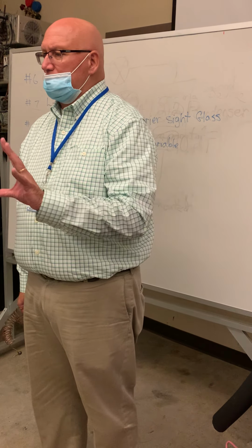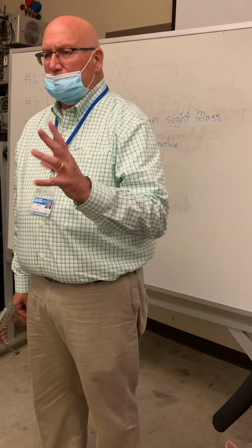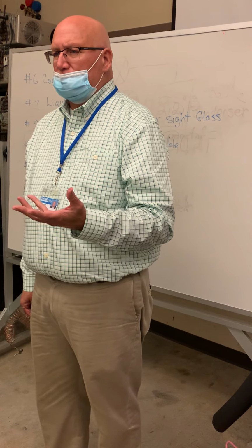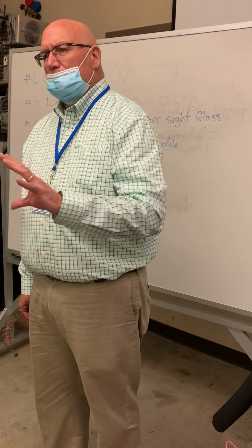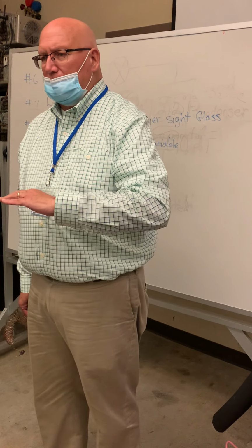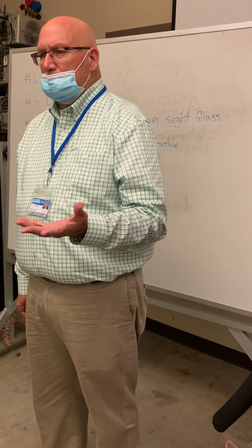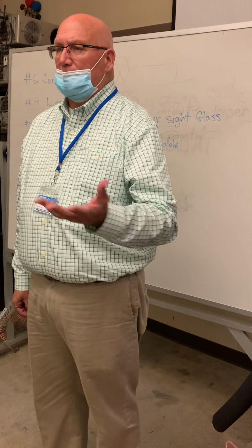Now, I'm using typical summertime temperatures, about 3 o'clock in the afternoon. So I know what the general ambient air temperature is going to be for Central Islip, New York, which is what we use at the airport. We use 85 degrees. That's the design outside temperature, we call it.